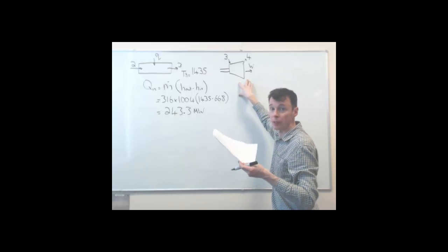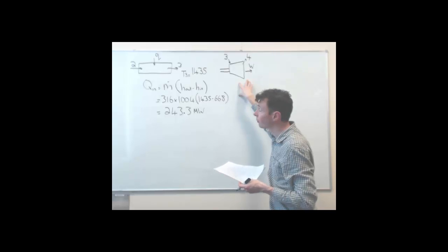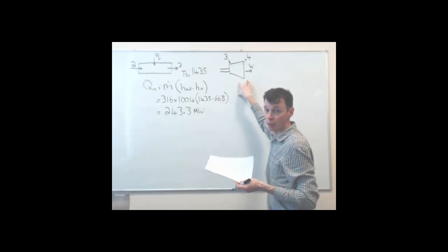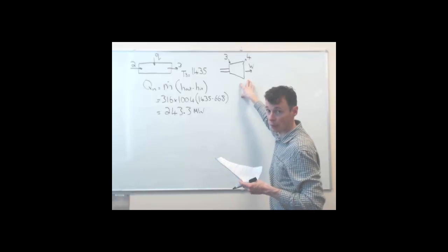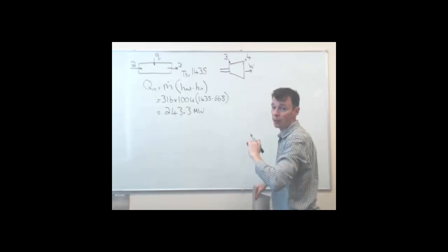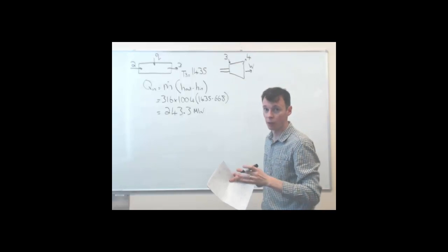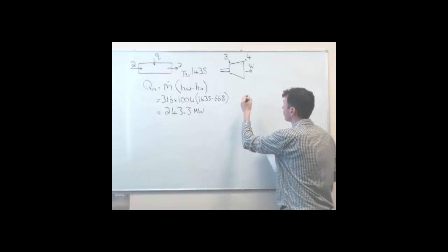You can go back through like we did in part A and work out the kinetic energy and then see if it is going to be significant in our answer or not. But for this point on the board, I'm going to neglect it once again. Okay, so this time no heat involved, just a work process. So again, no potential term, we're going to neglect the kinetic term.